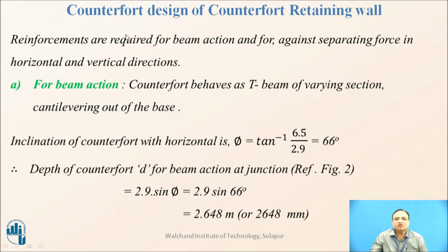Now the reinforcement is required for beam action and against separating forces in the horizontal and vertical direction. For beam action, this counterfort is nothing but a beam. The counterfort behaves as a T-beam of varying cross section, cantilevering out of the base.